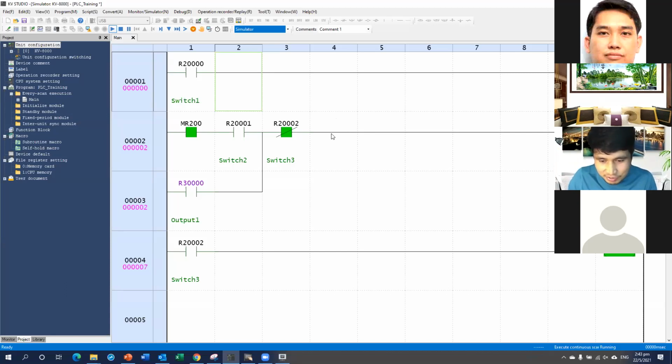If your PLC is PNP, your switches should be PNP also. If your PLC is NPN, your switches are NPN, and you need to convert it through electrical diversion. You cannot directly put a PNP switch to an NPN PLC. It will not work.